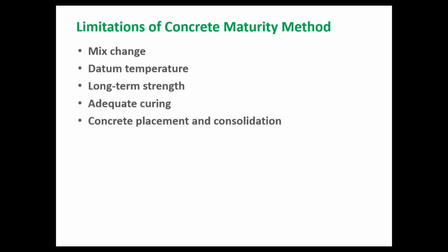The other thing is placement and consolidation. If you're not compacting concrete well enough, it cannot be captured by maturity, because maturity is only monitoring your temperature, and it cannot capture the voids or other things that are happening in the field. So just be mindful of that.